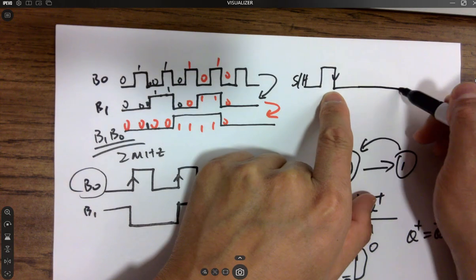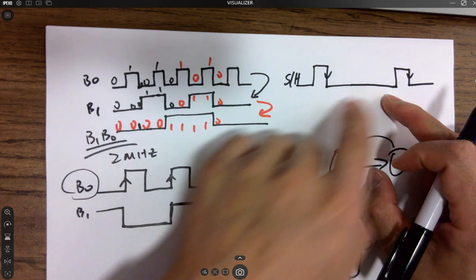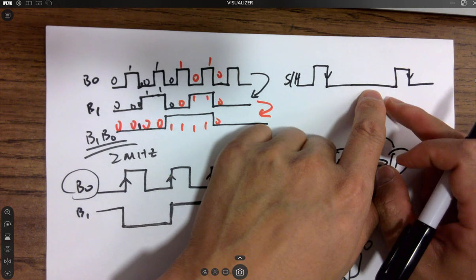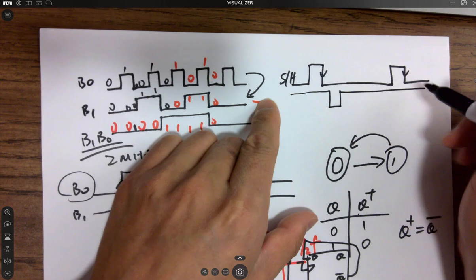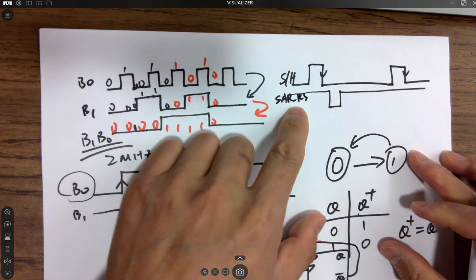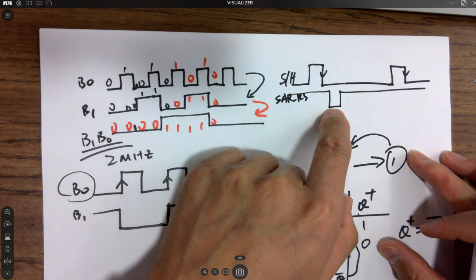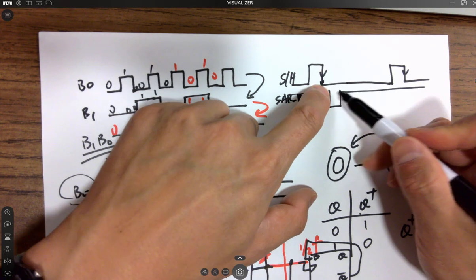And we need to go through a certain number of cycles. We need to do this again to sample another one. So in the middle, we did the end of conversion kick out of the door, and right behind this, we need to do a reset of the SAR. Set and reset. Remember, we create that 1 and all zeros code. Right after this data is available after the falling edge is ready, we do this, right?